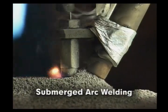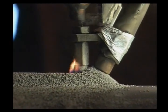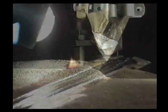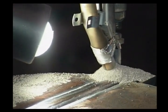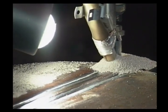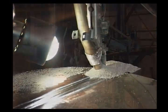In submerged arc welding, a bare, continuous consumable electrode wire, shielded by a layer of granular flux particles, sustains the arc. When the arc is struck, the tip of the electrode is submerged in the flux, and the arc is not visible. Welding proceeds without the intense radiation that characterizes open arc processes, and with little fumes.